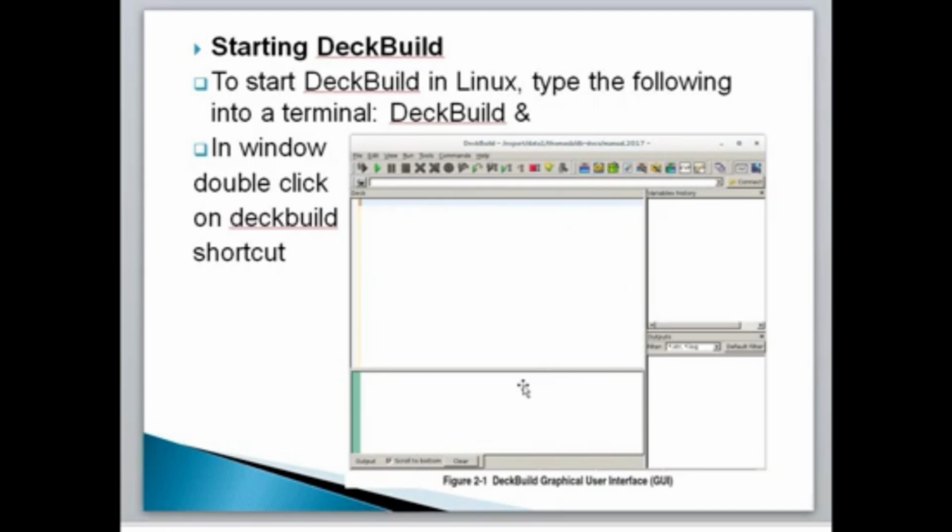The upper portion of the window is the deck editor window, where you can either type in the syntax directly or display syntax from a loaded deck. The lower portion is the RTO, runtime output, and the lower side portion shows the saved log and structure files. This will display information generated from the simulation run. The very top is a range of drop down menus and a toolbar, which contain all the shortcuts.